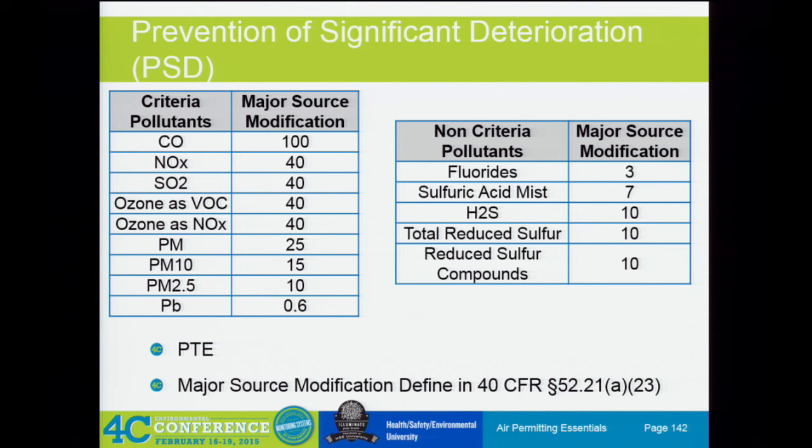And so if you are an existing major source under PSD, you don't necessarily have a PSD permit at this point, but you're making a change at your facility that is a major source. So we'll talk as if we're a refinery chemical plant in this instance. So we're above 100 tons in NOx, CO, or VOC, any one of those criteria pollutants. And we make a modification at our facility. We now look at the modification levels. These are these significant impact levels that we talked about earlier.